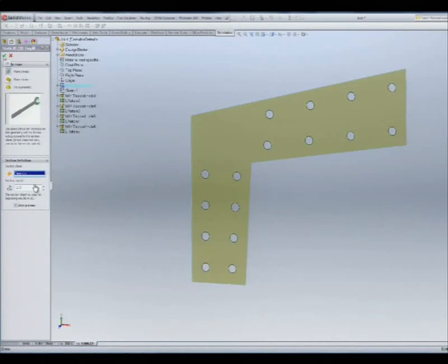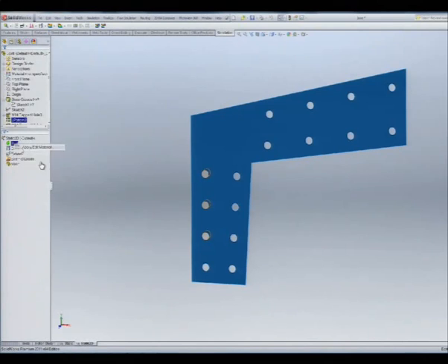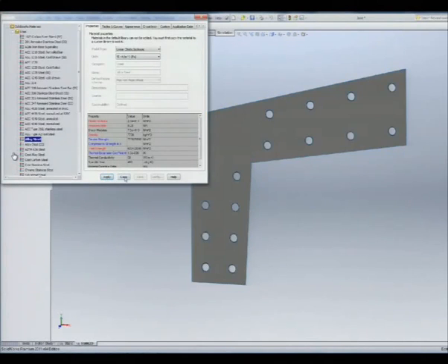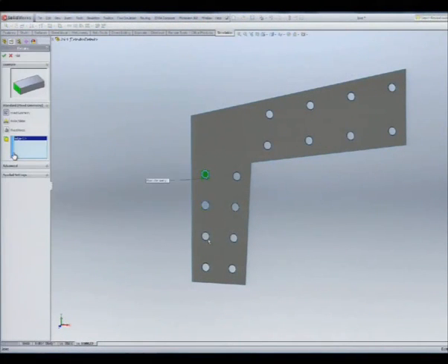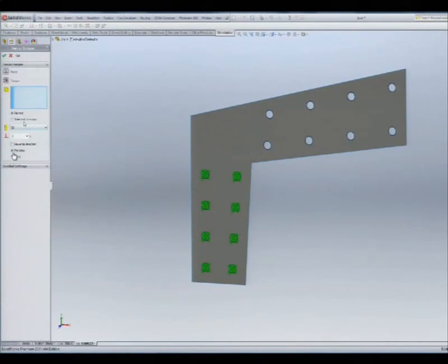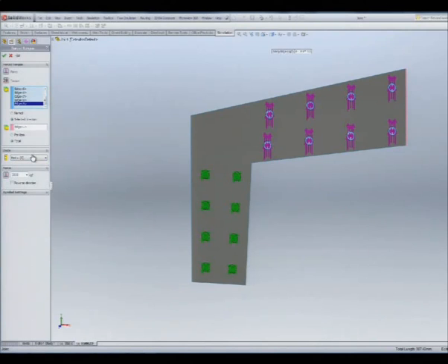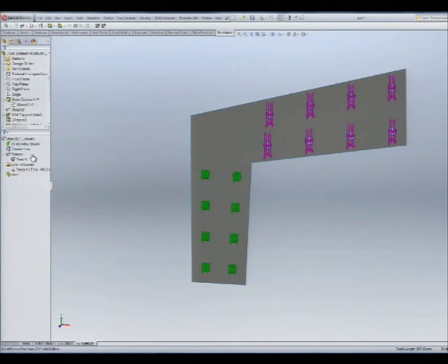So I have to decide the plane and the width of the plate, and this is similar to what we already did. Material, boundary conditions. Now I'm assuming that this is on a rigid column. So I'm fixing the 8 holes, and on the other 8 holes I'm putting the shear force that I got from the diagram, right? This is very usual for civil engineers that design joints. They design joints separately from the actual model, right?